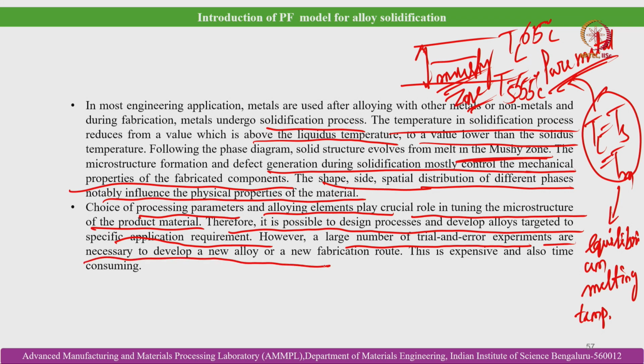Like we discussed in case of CFD based process model development, this mesoscopic phase field based microstructure model can also significantly reduce the time, cost and energy involved in trial and error kind of experimentation. Rather, it can provide deep insight into the physics of the phase transformation, and it can also predict the process conditions that need to be adopted to achieve the desired quality characteristics and desired microstructural morphology.